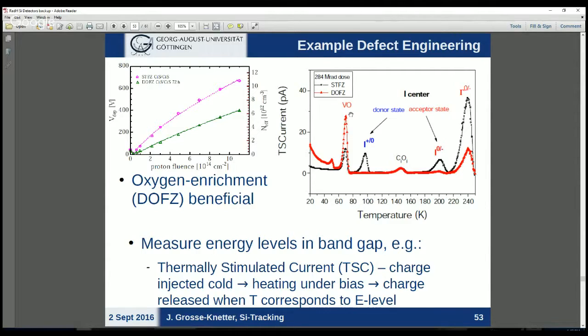For the sensors, it's almost the same, with a bit more interaction. IBM knows very well how to make chips. We have a few specific wishes in terms of making them radiation hard, but that's a very straightforward trick. For the sensors, it's on a similar level. We do the design, we being the physics institute: the size of the pixel electrode, what's around it, and some special aspects to cover the edges of the sensor. So basically the mask and the doping profile they have to apply.